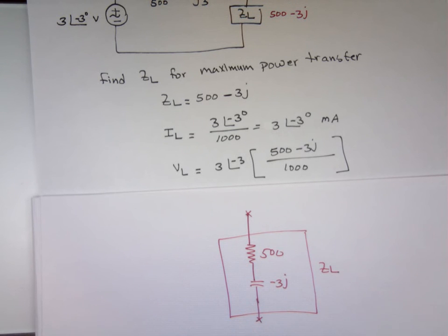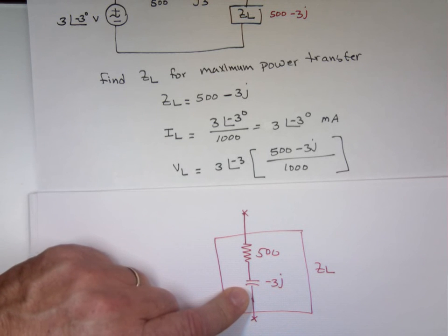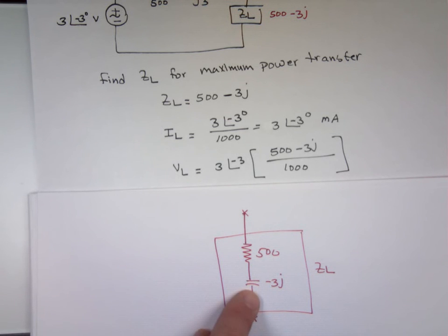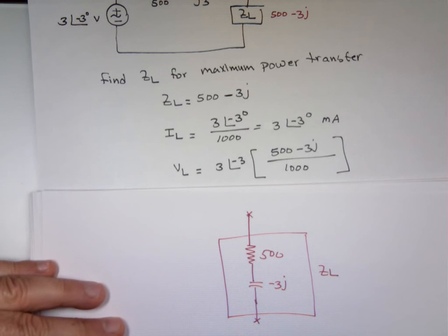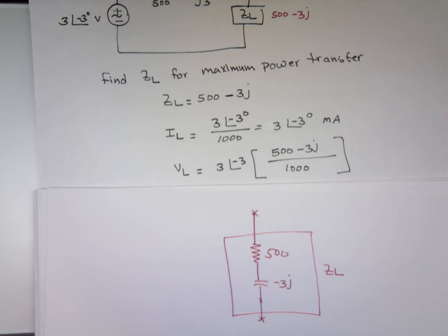And if you recall, we said last time, if you only have a purely reactive load, like a capacitor or inductor, the average power is what? 0. So the average power absorbed by the capacitor is 0. What about the average power by the resistor? Last time we derived that. Not p of t, the average power, not instantaneous. It's 1/2, you can use I squared times R.